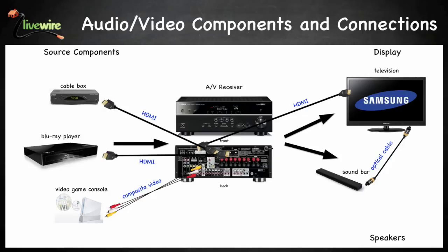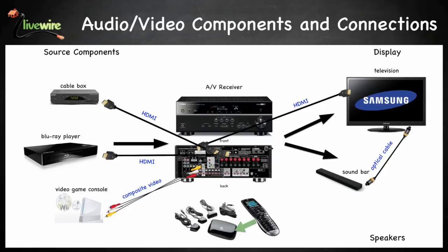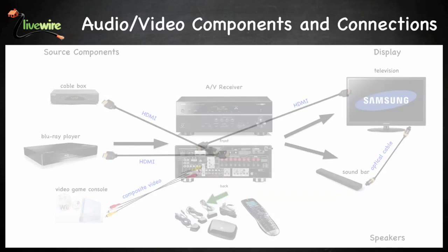We have one more piece that we must include for the home theater system, a remote control. Most often, the remote control will come with an IR transmitter to control the various components. In addition to placing the transmitter in close proximity to the various components, you may have to run an IR extender from the transmitter to the television. We use Goop to attach the extender to the television in a location that will allow the signal to successfully control the TV. That's it!